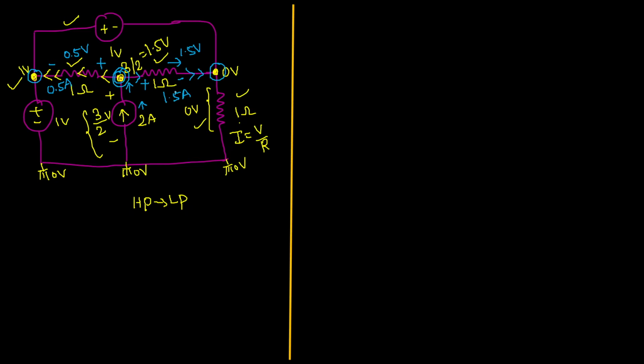Either you can go in this way, or what is the alternative way? Sir, you know there are three branches. From the lower branch, 2 ampere current is coming. Already you found through the left side 0.5 ampere is going. If you apply KCL at this node, it will clearly tell you out of 2, 0.5 ampere is going in this direction. Remaining 1.5 must go in this direction only. That is the alternative way. Next, okay sir, 1.5 ampere is coming here. That we have figured out.